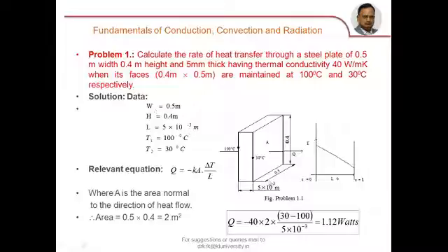The data given is: width of the plate 0.5, height of the plate 0.4 meters, the thickness denoted by L is 5 mm, 5 into 10 power minus 3 meters, one face is at 100, the other face is at 30. You are asked to determine the rate of heat transfer through the plate, which is nothing but by means of conduction.